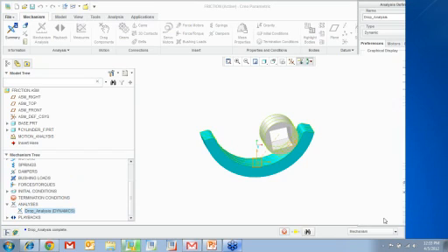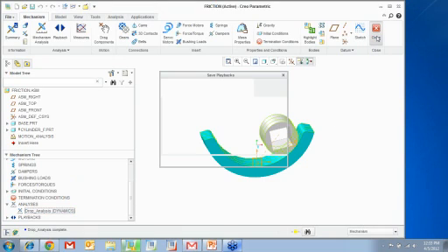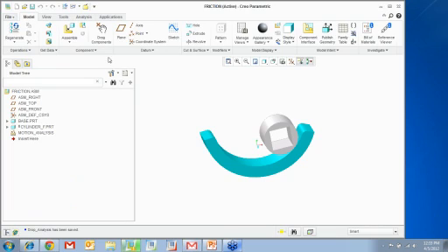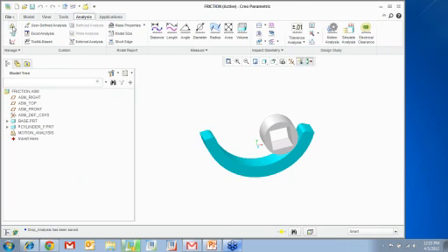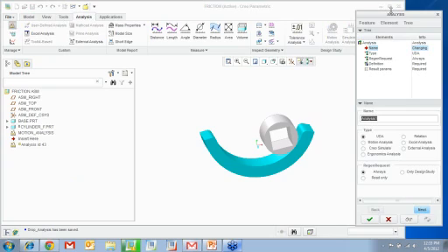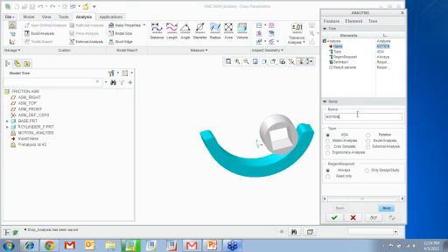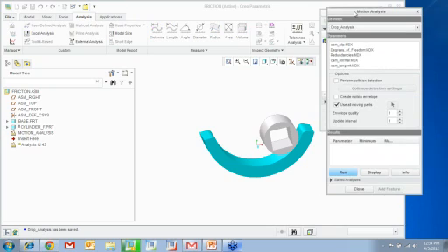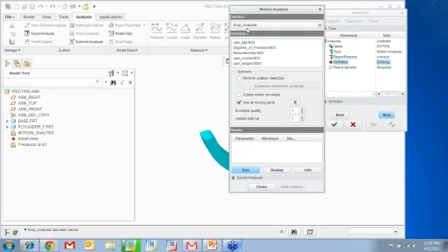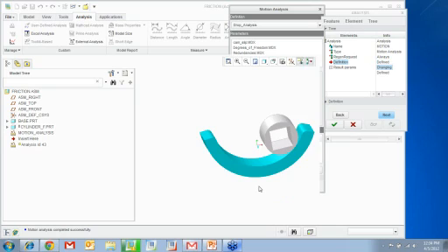Now, so this is my particular analysis. I'm going to close this. I'm going to go in here to analysis, and let's call it motion. Say it is a motion analysis right here. Say next. So notice that from MDO, it finds out that you've run a drop analysis. Run it. Just going to run it in the background. And you can close this.